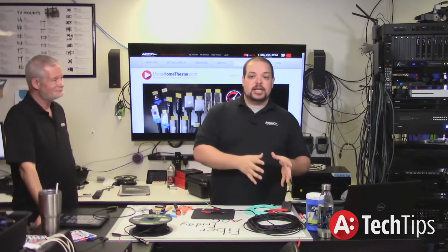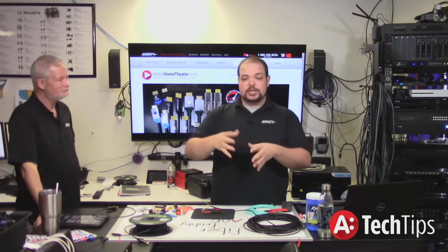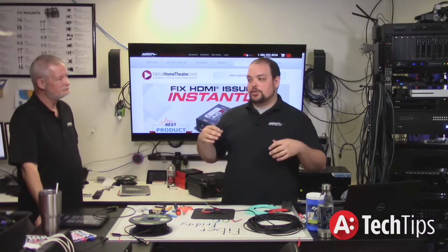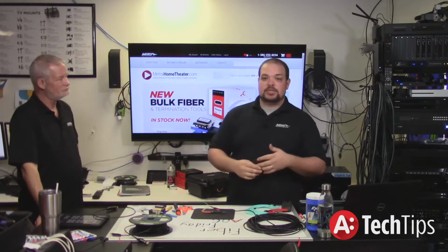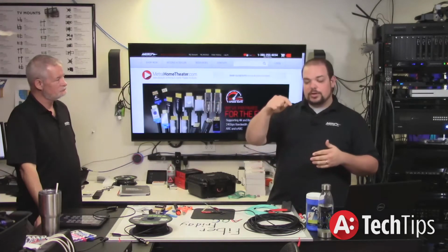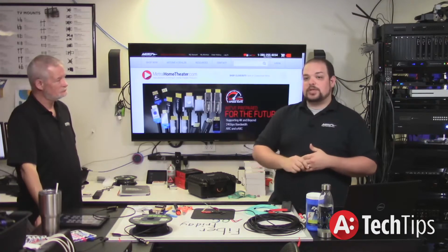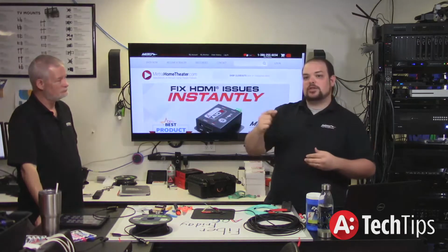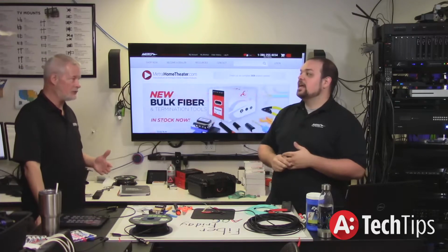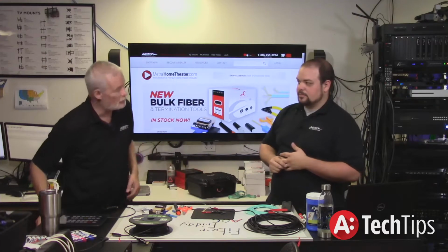So it does make a big difference, because basically we're trying to save money at this point when you're doing the installation. If you do a straight fiber connection, all of that has to be done through a processor of some kind. The source says, hey, I'm sending 5 volt to the TV. Well, then your HDMI transmitter over fiber has to come up with some way to tell the receiving side that, hey, send 5 volt to the TV.